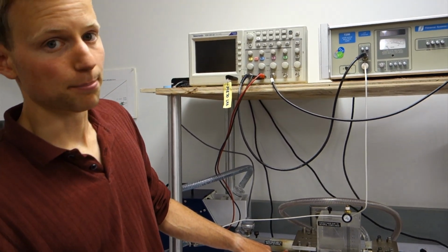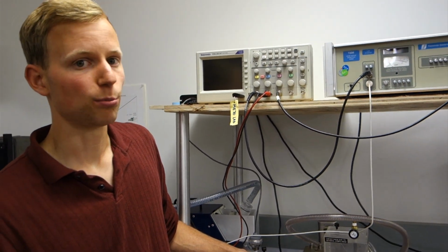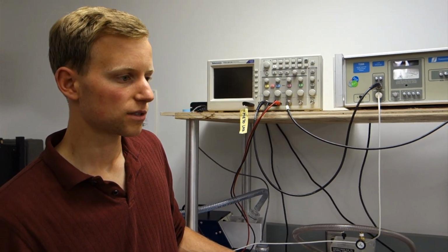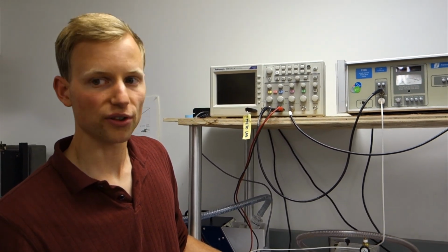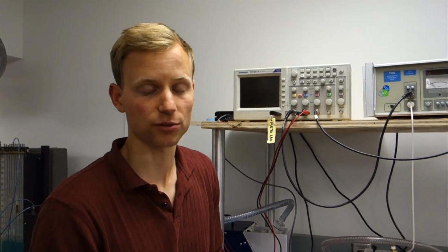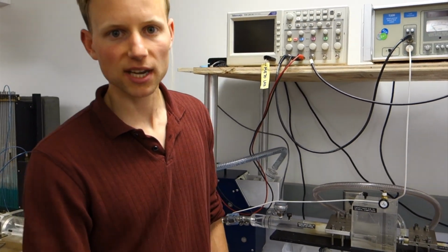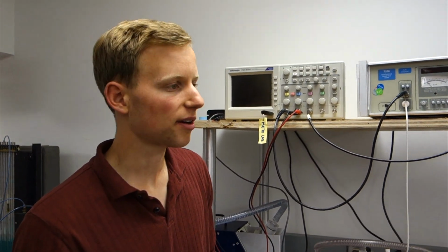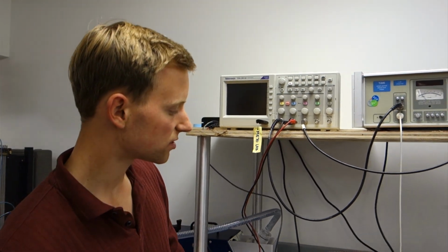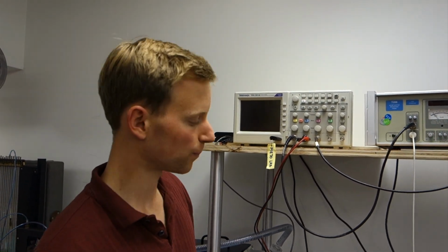And note that was using blood for your working fluid, so mu blood instead of mu water. So if we want to use the current experimental setup, which includes water instead of blood, we need to divide by the ratio of mu blood to mu water, which is 4.6. So you should get about 1.3 millimeters of mercury per liter per minute for this R1, analytically.